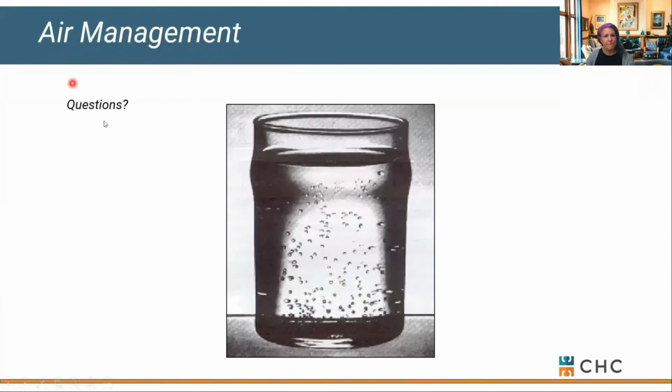Okay, Sunday, forgive me, this is a really good chance to look at some questions before we kind of wrap things up on the air side. So question from Ryan Callahan, what are some things that can cause a bladder to fail? Yeah, good question, Ryan. So one of those might be welding slag or debris in a tank. If there's manufacturing debris that's sitting in a tank, then that can cause premature failure. You would typically see that within warranty period or relatively quick.